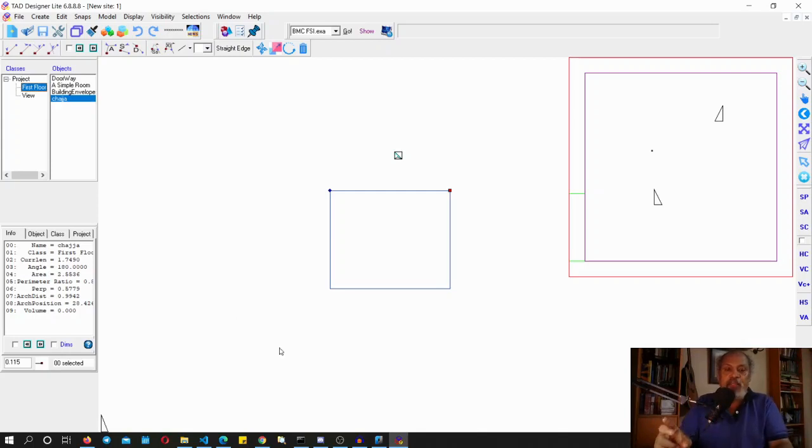So let's do the same thing here. What I do is that wherever the first helper is, take a look at the mouse now on the screen inside TAD. Now what I'll do is that I'll press Control Backspace, which is a command to delete that particular vertex. And this is removed. So you can do it with this particular button also if you want to. But Control Backspace is, I think, good enough. So immediately, just like the way you saw here, it has become a triangle.